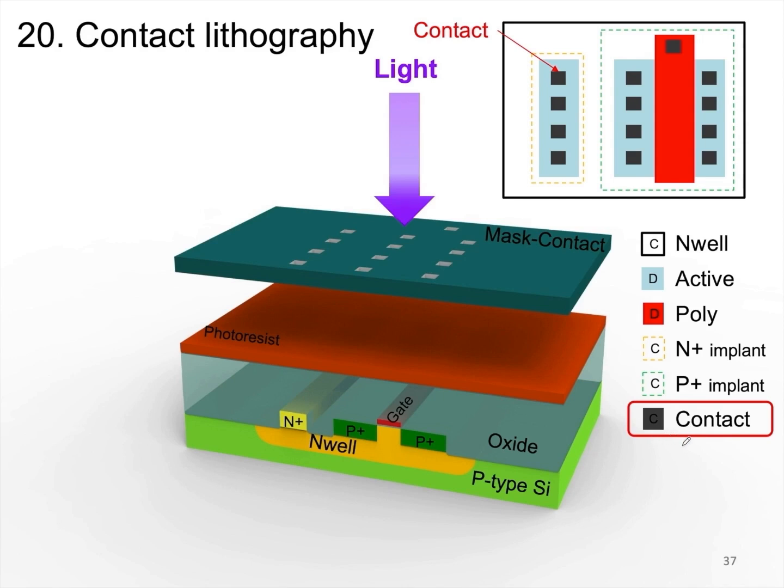First, we need to deposit metal on M1, so M1 will be connected to our metal. Then, we need to keep our interconnect lines intact. After that, we will spin coat photoresist on M1 and etch it. The etching process means we need to keep the patterns we want, which are the necessary metal interconnect lines, while removing the unnecessary ones. So during the photolithography process, we need to retain some of the interconnect line patterns.